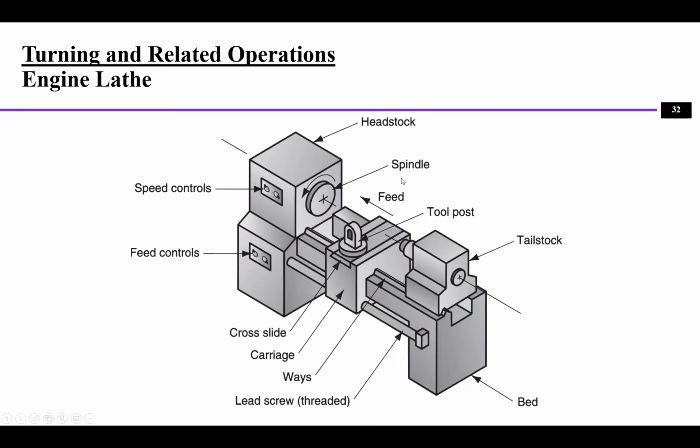And this is a spindle, and typically what we do is use a clamp to hold the part, and then when the spindle spins, the part will spin as well. And where's the tool? The tool is set up here. One motion is the spinning of the part, another motion is the moving of the tool. Using the combination of the two motions, it can help us to create the geometry of the product. And the tool can move left and right, and in and out, so both directions.